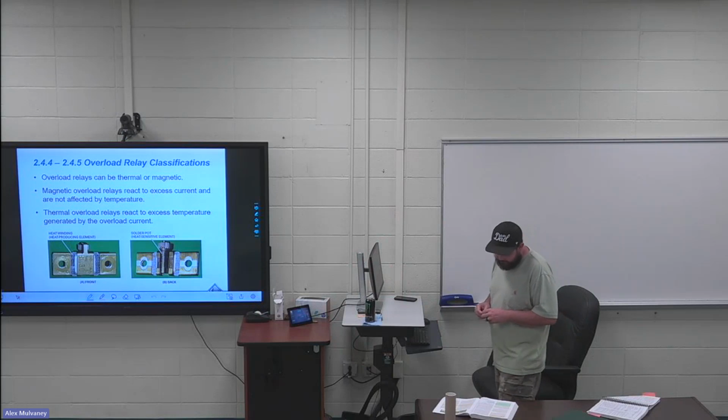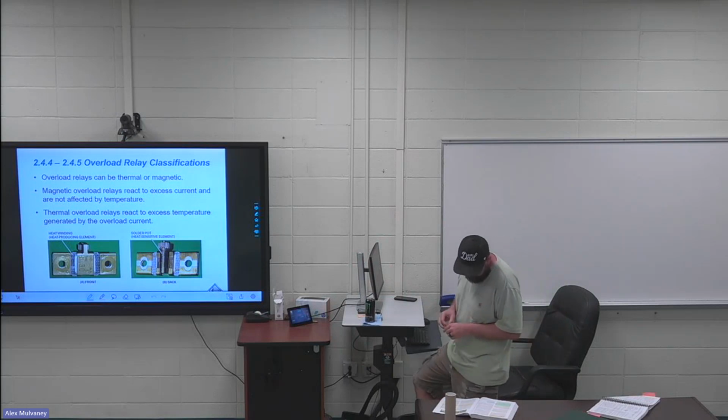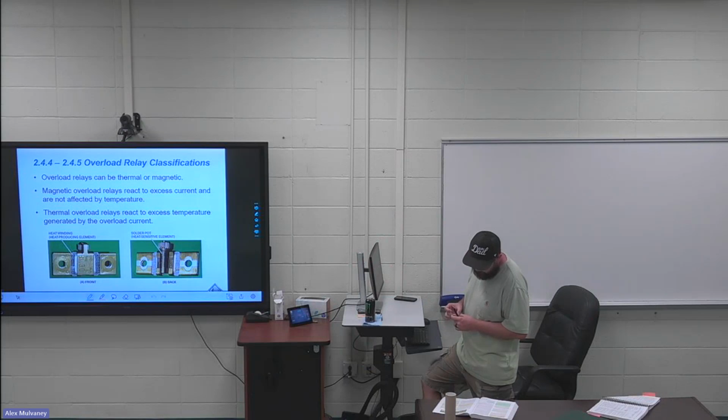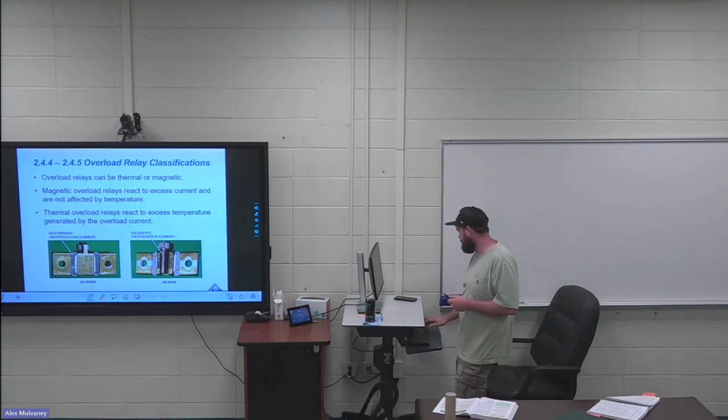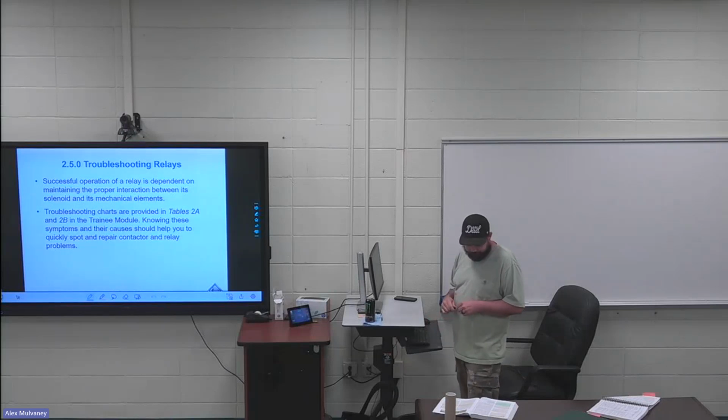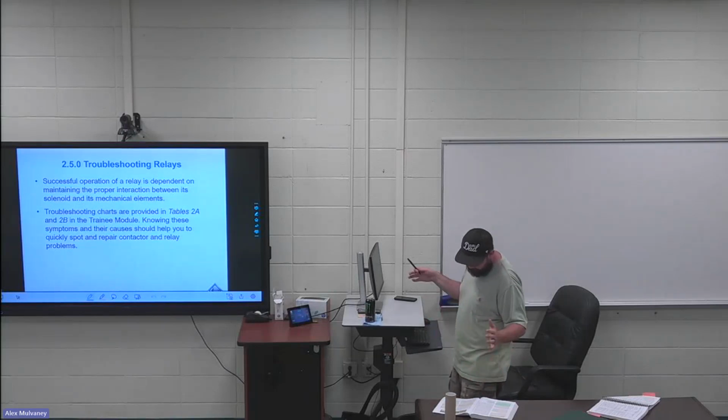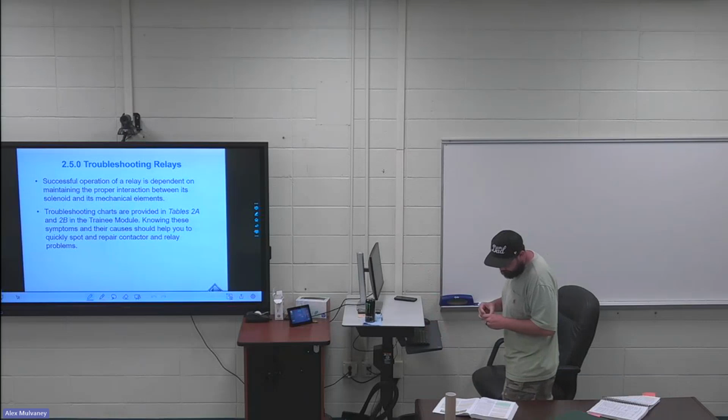250, troubleshooting relays. Second paragraph, first sentence is highlighted. The operating coil is usually designed to operate the relay from 80 to 110% of the rated voltage. So voltage shouldn't be a big deal in operating these relays, because that's a wide range of operating voltages.